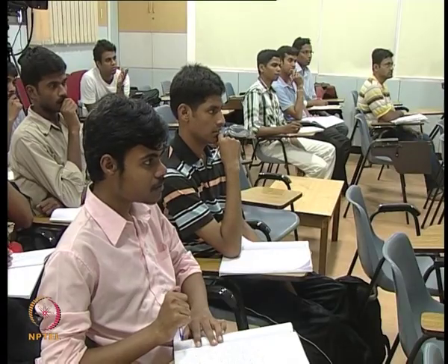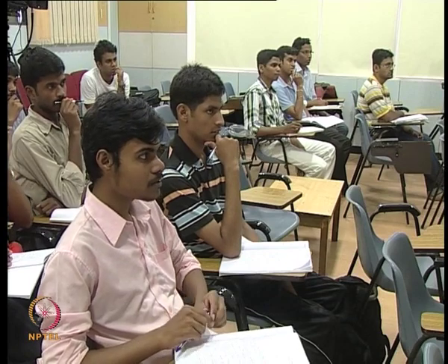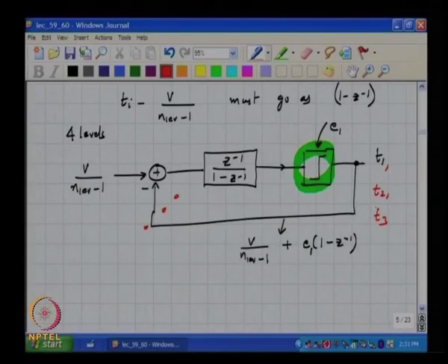So if you didn't know all of that, can you look at it straight away and say this got to be insensitive to mismatch? No, if T1, T2 and T3 are all identical, right, then the output waveform of the DAC will be only a 2 level sequence, correct?